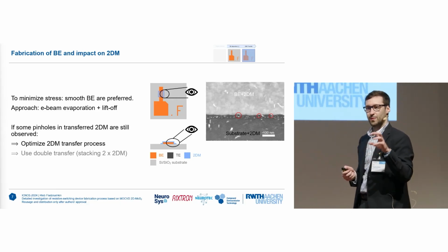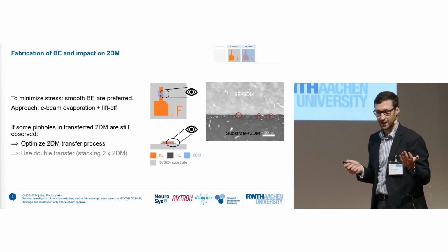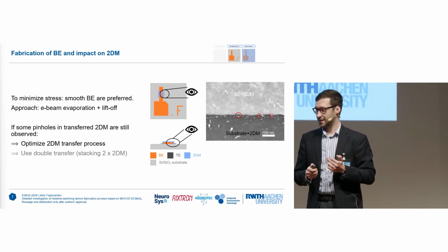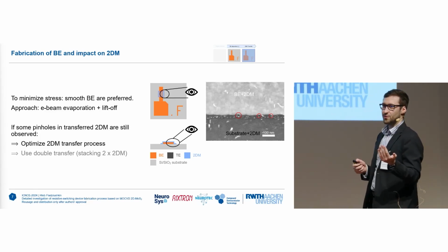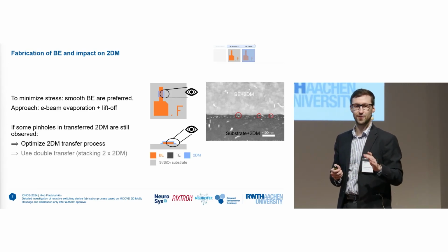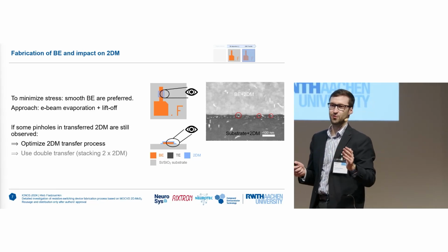So there you might get formation of very small pinholes. You can see from the scales, they can be 10 nanometers small, which can as well really kill the yield of your devices. So there are two approaches. The first one, quite straightforward. You can think of just transferring the second layer on top and hoping for the pinholes not to overlap.